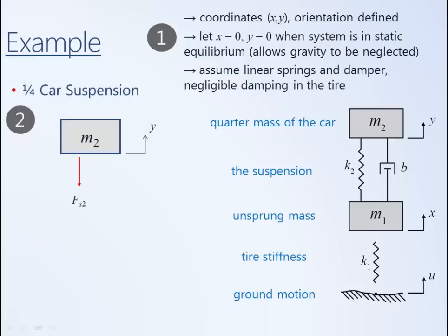And so I orient my spring force to be downwards. Similarly, with the damper, I imagine that M1 is fixed and that M2 is moving upwards, and since the damping force opposes the direction of the velocity, the damping force will also be downward.